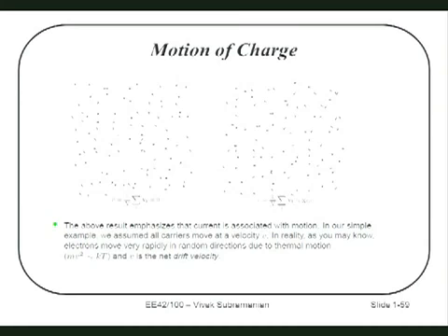Then, what does this mean? How can I talk about counting electrons? What am I saying when I'm saying I'm counting electrons? I'm saying, on average, despite the fact that the velocities are going all over the place, if I were to average out all the velocities of all the electrons, there will be a net velocity vector in a given direction. And if I put positive 1 volt here and negative 1 volt here, the net velocity vector would be in that direction. Not all the electrons are instantaneously going in that direction, but average all of them out, and they will have a net velocity in that direction.